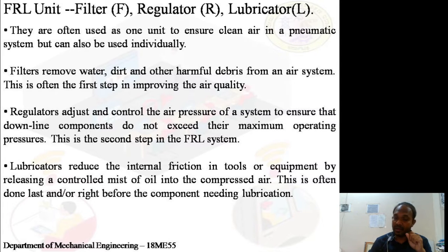Okay, the hissing noise, you can even hear it in buses also. The hissing noise you hear from the pneumatic system is always the sound of air relieving from the system. A non-relieving type will not do this. A regulator should be chosen based upon what kind of pressure or flow requirements we have and even the nature of the work that we are looking out for.